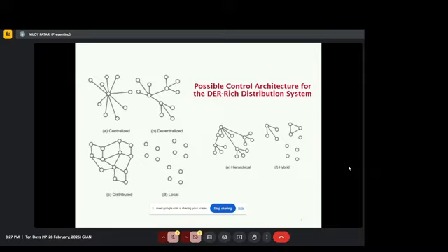In the ADMS, there is an optimization solver or whatever there is, and they will compute decision variables. Decision variables meaning what taps should be, whether capacitors should be on or not, what the set point of the battery should be, and all of that. And then they will send those set points back to the agents.